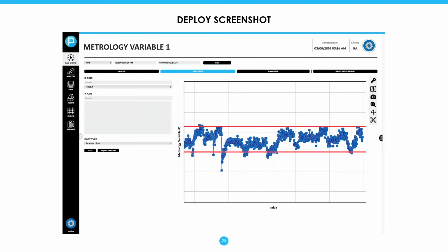The residual plot, which again is the actual minus predicted, you can see here we had 2 thresholds. Again, this is plus or minus, I think about 1%, which might have been 0.02. I'm not quite sure what it was exactly. But again, you can see that most of the points are within those acceptance criteria, with a few outside of that. The ones that did fall outside of this were mainly due to warm-up effects or temperature effects, and these are challenging problems to avoid.